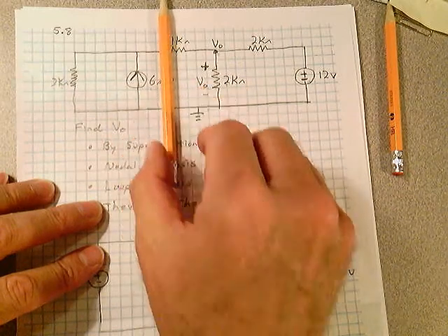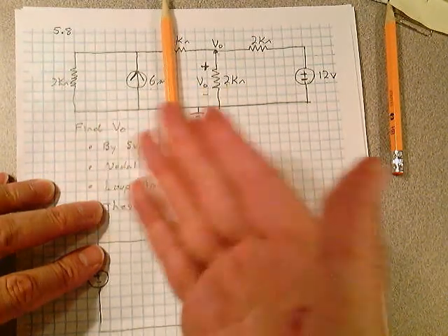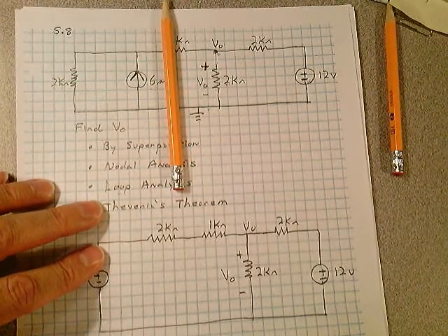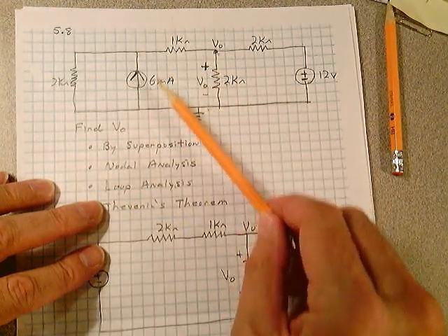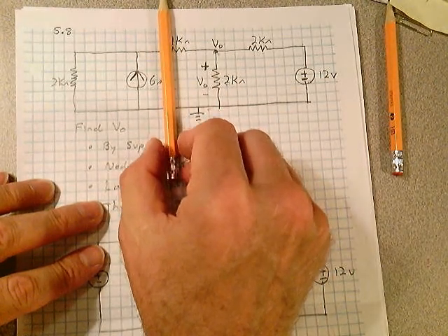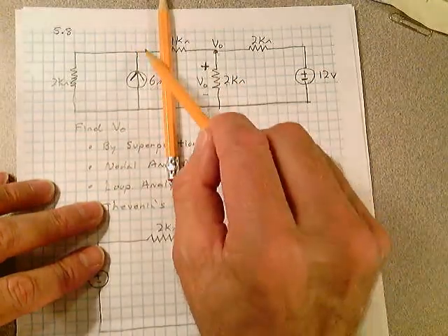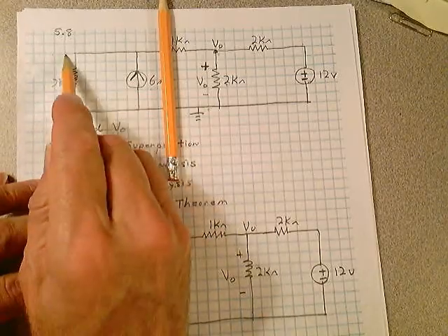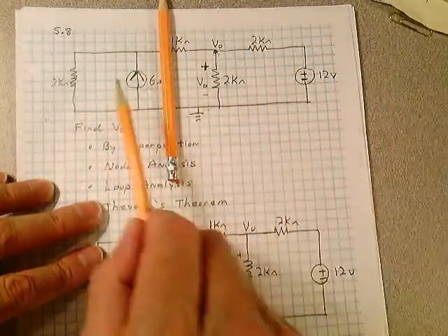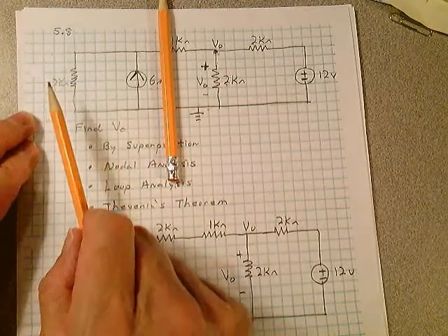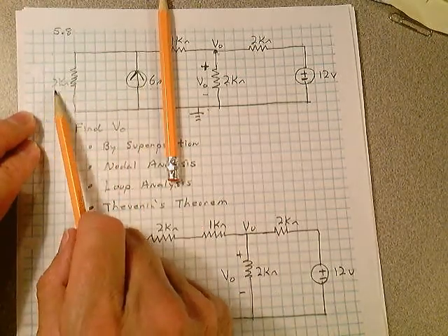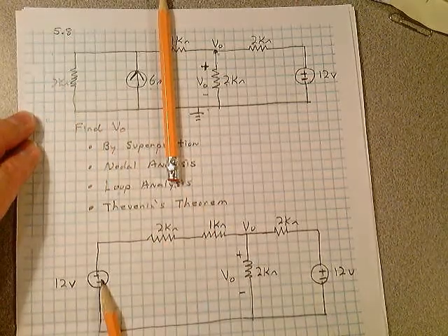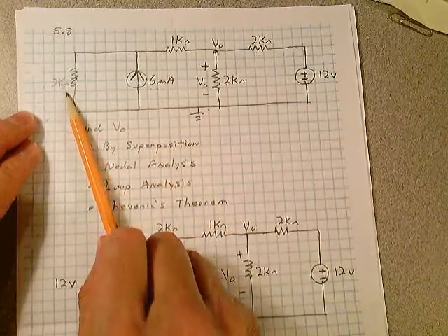Everything to the left of my pencil is just a current source, a Norton equivalent, if you will. I'm just going to find the short circuit current between here and here. Okay, I'm sorry, I'm going to find the open circuit voltage between this point and this point. Or if you prefer, here to here. It's the same voltage if this is a reference. I'm just going to convert this to a voltage source, and I do. 6 milliamps times 2k ohms is 12 volts, and I bring the 2k up.